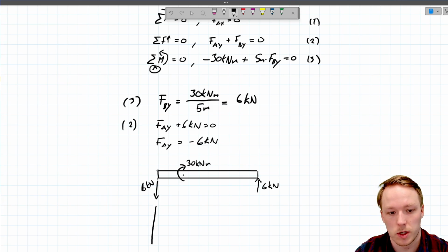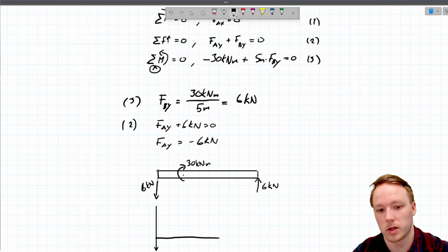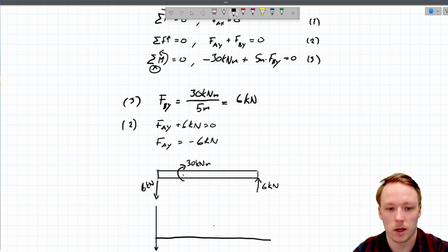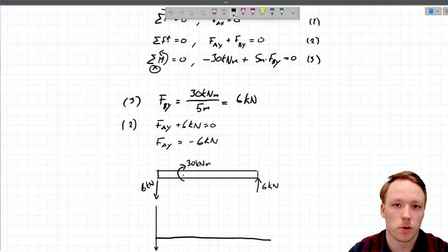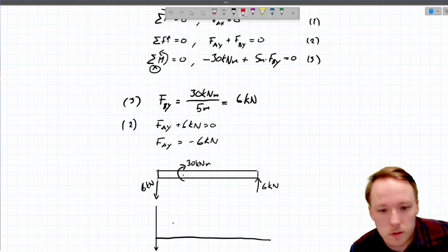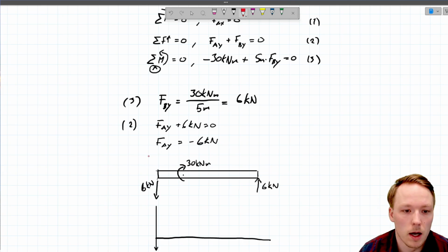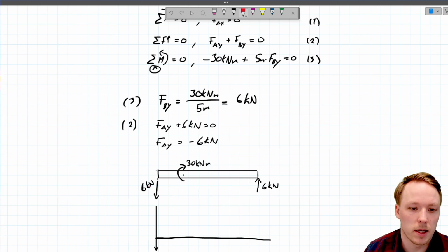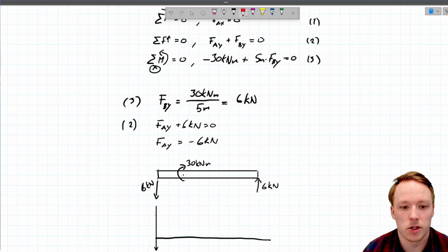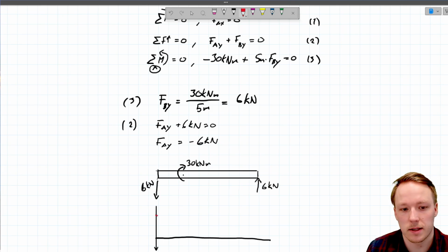Next thing is that we must draw the shear force diagram, because we are going to need the internal shear force to calculate the shear force between the layers, caused by bending. At the beginning we have an external force pointing downwards, which means that the internal shear force will be in the opposite direction, towards the negative direction.